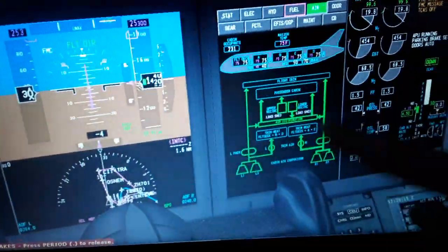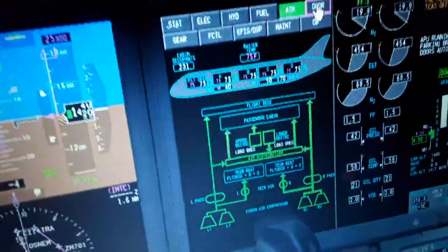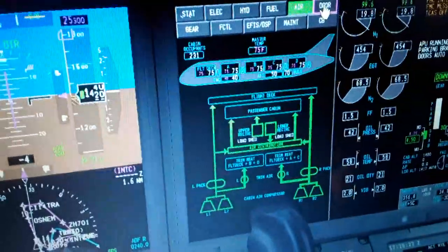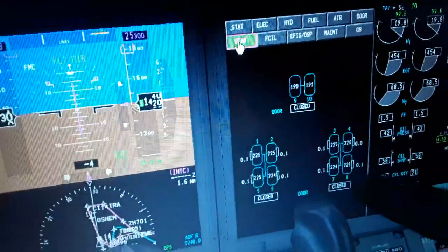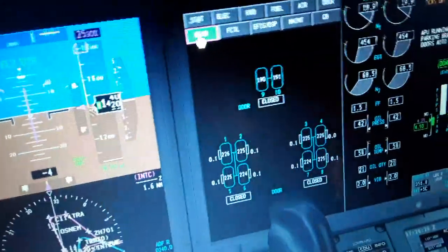We have the packs left and right. Packs, engine, pressurizer, oxygen regulation, the doors are closed, the cabin can be pressurized, landing gear, temperature of the brakes and pressure of the tires, flight control. You can see the flight controls movement. Last thing we need to do here in this small checklist before going into flight.